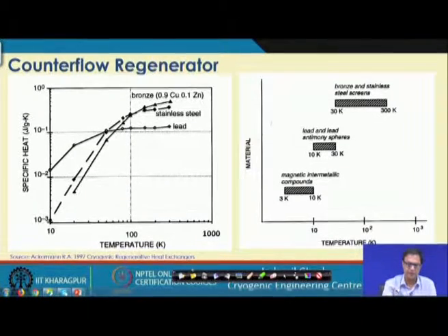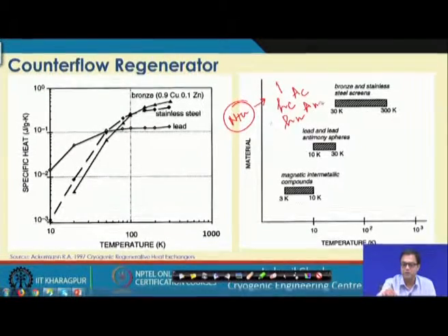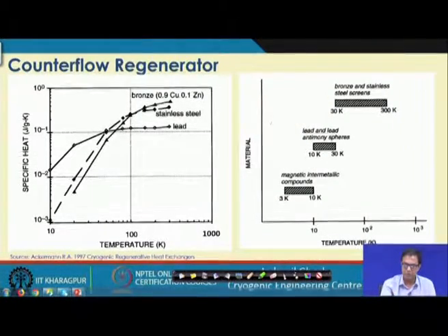Other than that, if we look into the NTU part, to make the NTU high, it is obvious that we should have a high heat transfer coefficient for the cold side and the hot side, and then obviously you have to put more surface area associated with both the cold and the hot fluid. With this we will move to the design part once again.